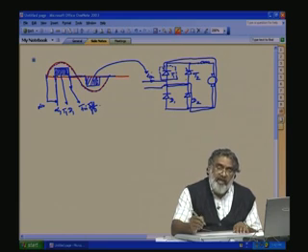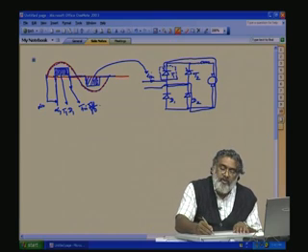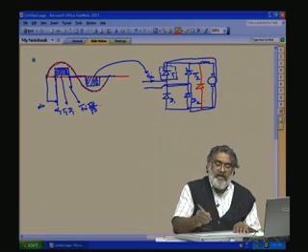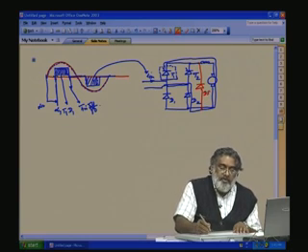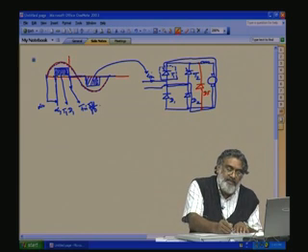So, to make sure that T1 is turned off, what do we have to do? We have to put another path, that is the freewheeling path here. We have to add a diode DF. So, during these input zero current periods, DF will be conducting.